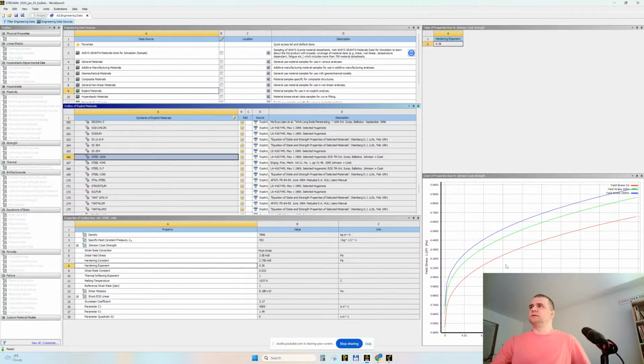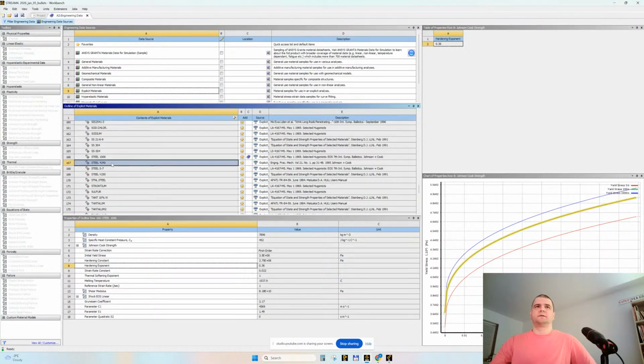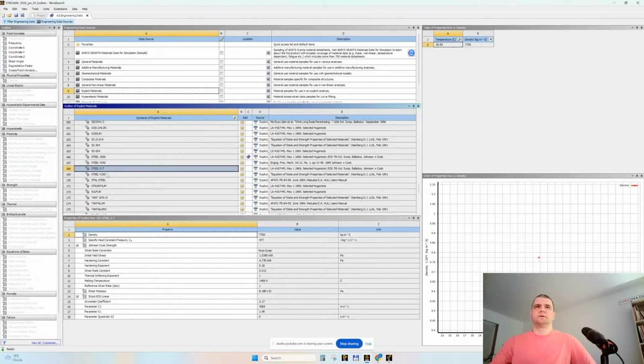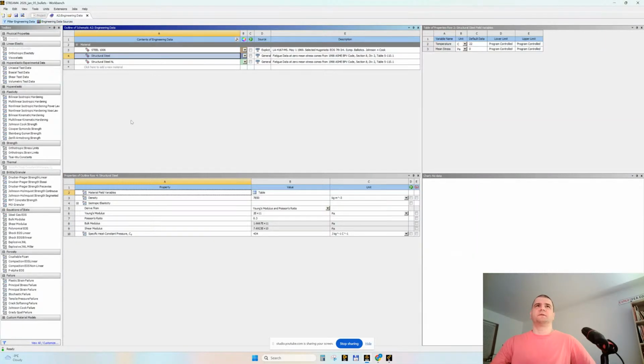I like these curves, stress strain curves. So we have one with Johnson-Cook. Let's add it to our library. And then let's go, do we have something different? Steinberg-Guinan. At this moment, let's stay with what we have. So we have three types of steel, let's say.